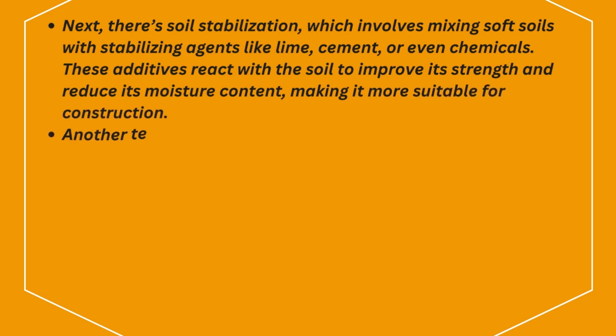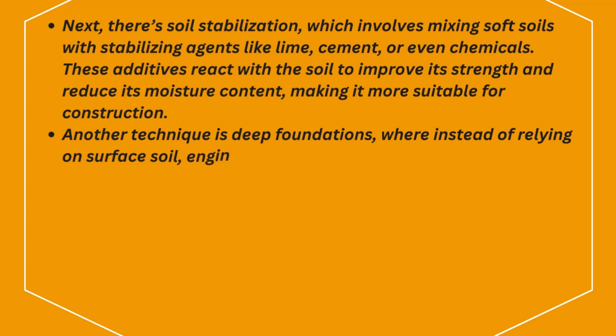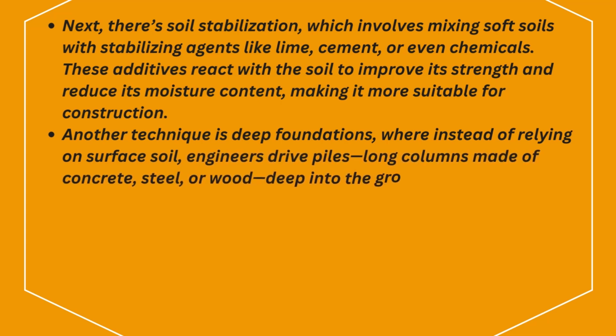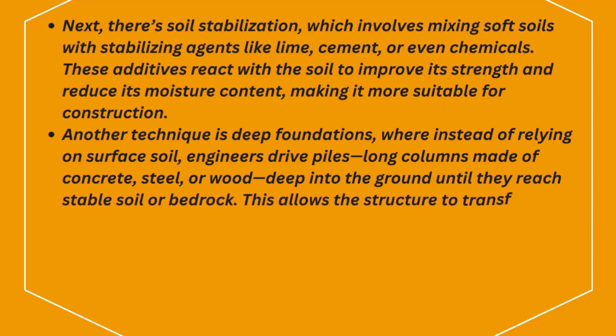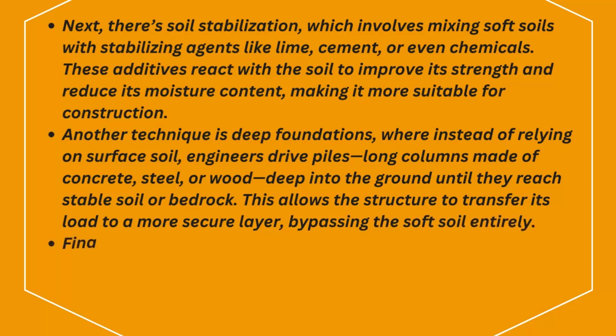construction. Another technique is deep foundations, where instead of relying on surface soil, engineers drive piles, long columns made of concrete, steel, or wood, deep into the ground until they reach stable soil or bedrock. This allows the structure to transfer its load to a more secure layer, bypassing the soft soil entirely.